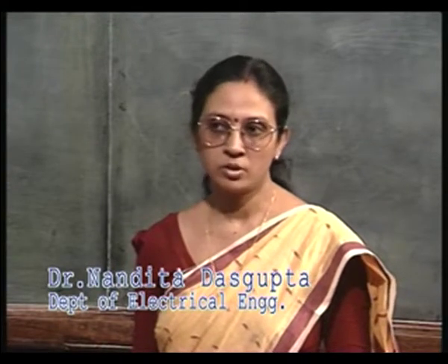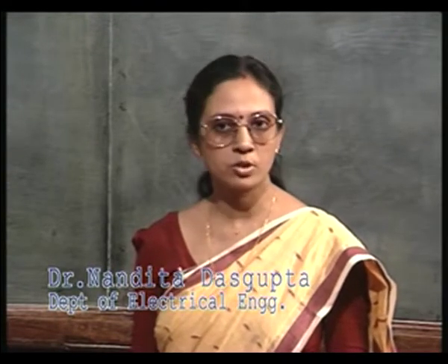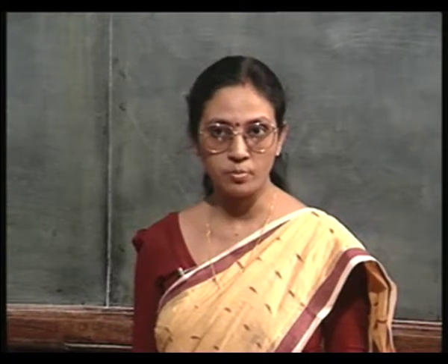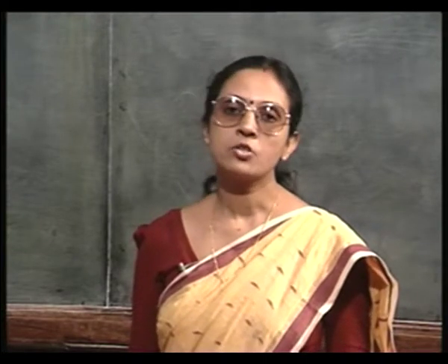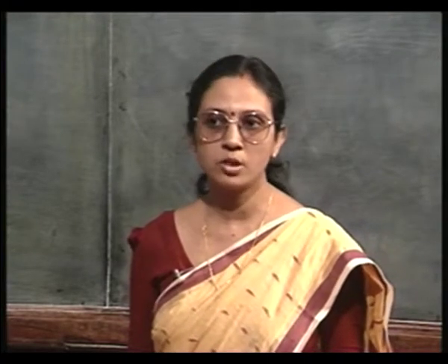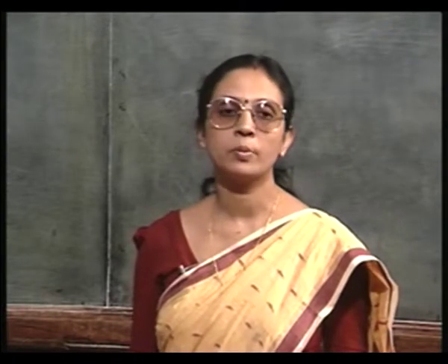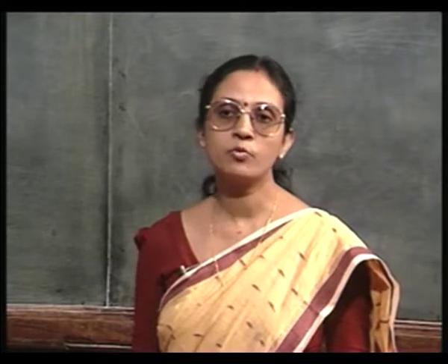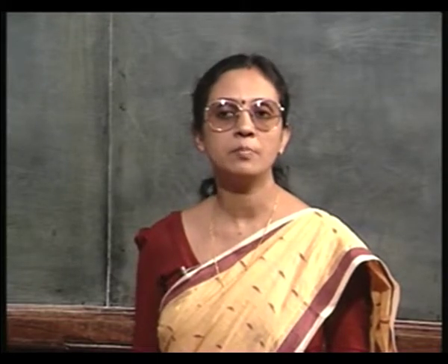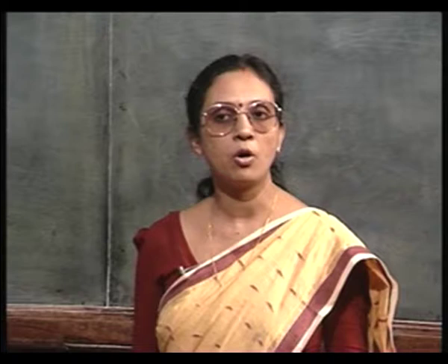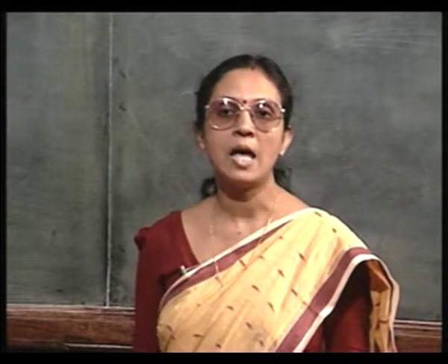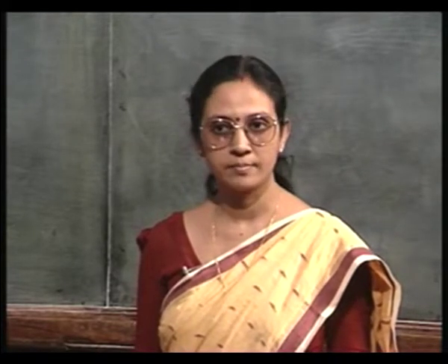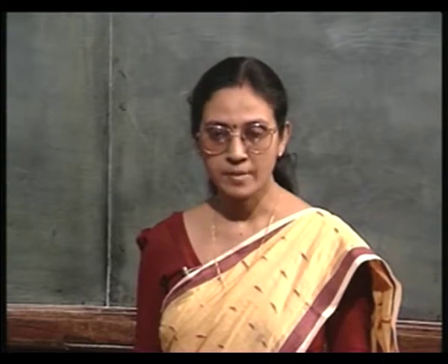If there are, let us talk about substitutional impurities, because they are the most important electronically. So, if we are talking about substitutional impurities, that is where the dopant atom is substituting for a host atom, there the movement is primarily governed by the interaction of the dopant atom with the available vacant sites, right.